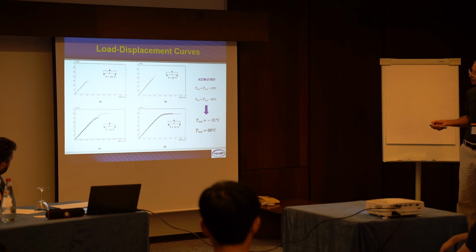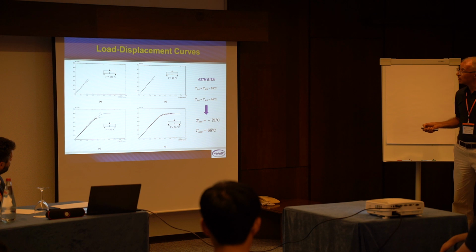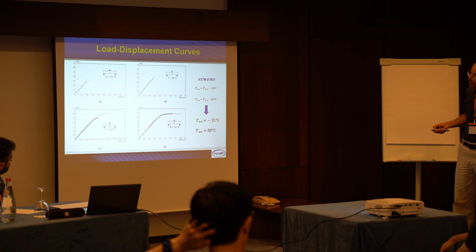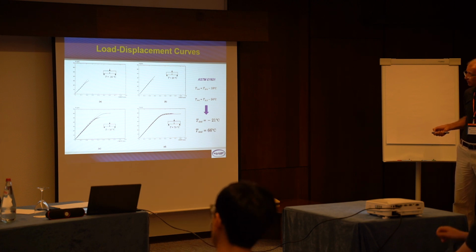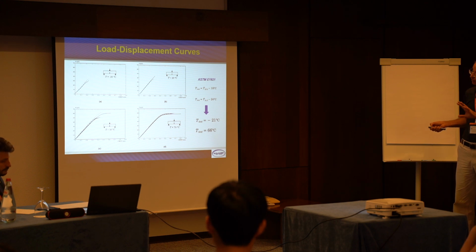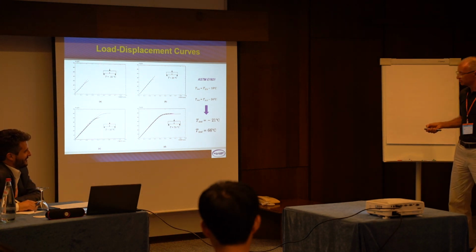At 20 degrees, just put your specimen on the machine and test it. It's room temperature; it's linear elastic fracture mechanics. So we start to get some plasticity at 50 and at 70. That's why this corresponds better to the estimate of the 41 joules. So this was also a nice outcome, because this will suggest to us what?